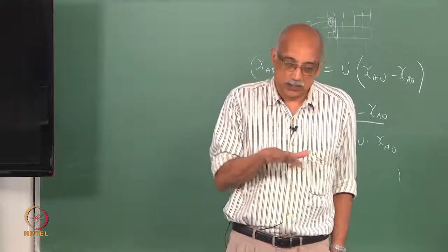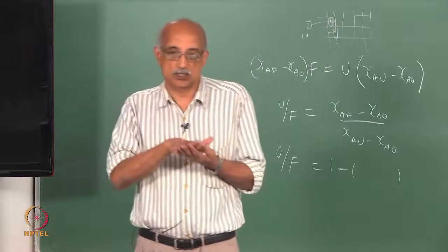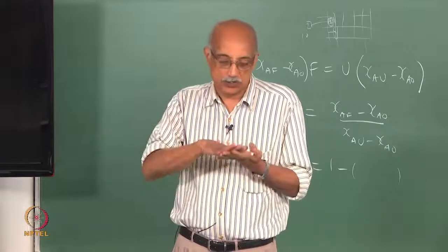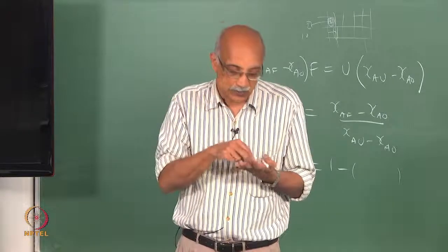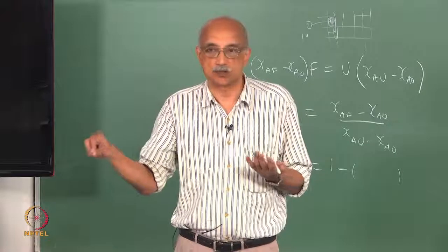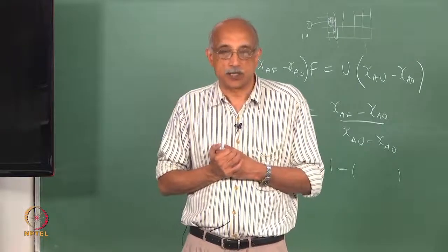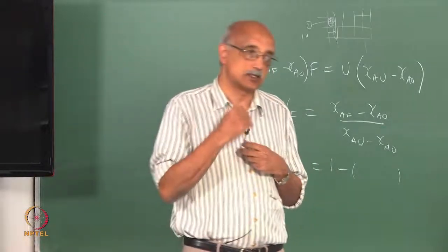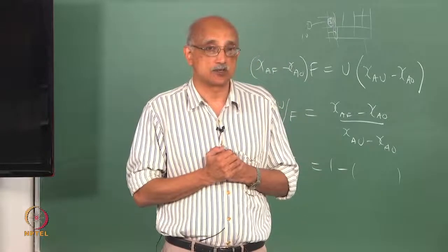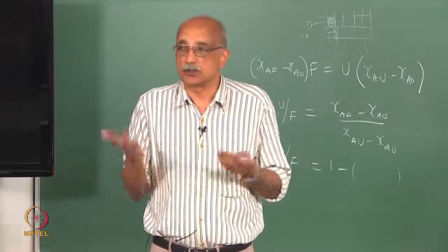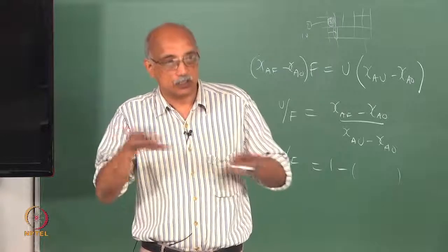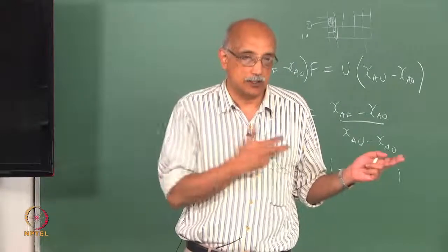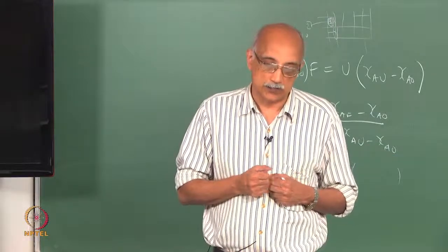The whole point in screening is until the particle actually encounters the screen, it should be unaware of the screen. That is kind of the ideal situation. So, it approaches the screen, it has a certain size, it sees an opening that's larger, it passes through, right. That is the way it is supposed to work. But if you actually start depositing some material on the screen, or you start having some deterioration of the screen because of processing conditions and so on, that is not going to happen. The changes in the topography of the screen can start having an effect on how particles get passed through. So, that again can impact your screening effectiveness.